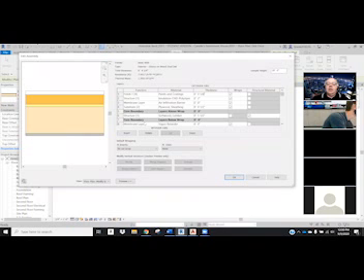Okay. All right. As I was saying, the reason I am putting in 1/8 of an inch is when we put color onto stucco, it's done with another colored stucco. So we put on 2 coats of basically grout, like you would for tile. The first coat's called a brown coat or a scratch coat, and is just there to give strength. The second coat has the color, and the 2 coats can be anywhere between 1/8 of an inch to 1/4 inch thick. And so this just kind of accommodates that for us.